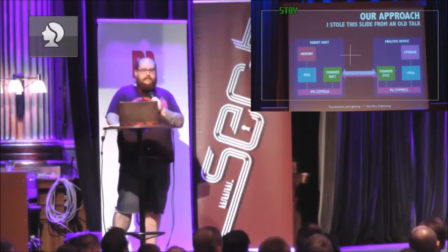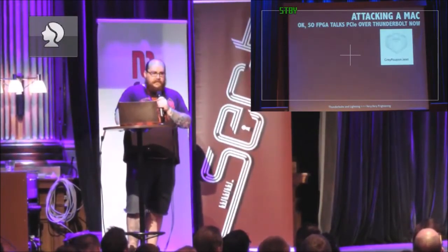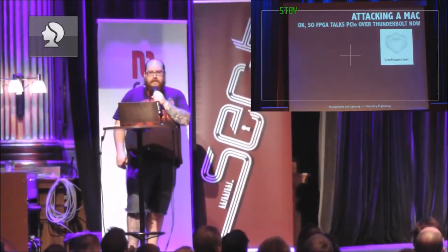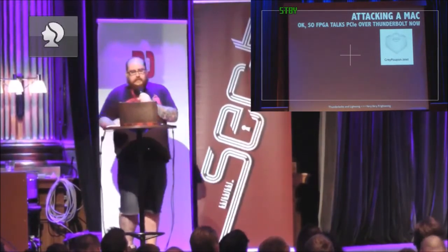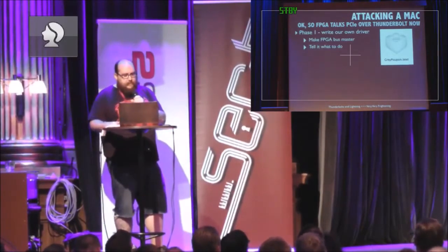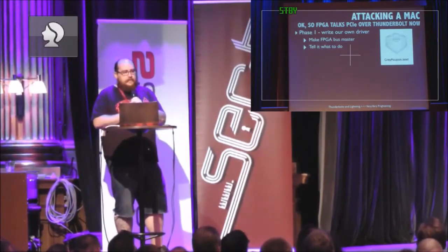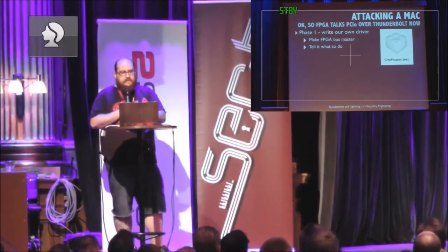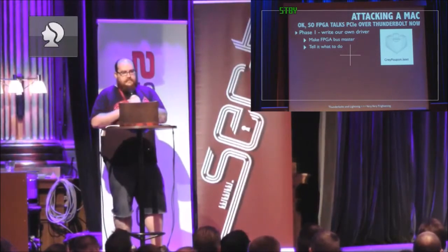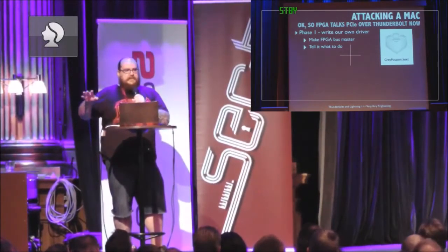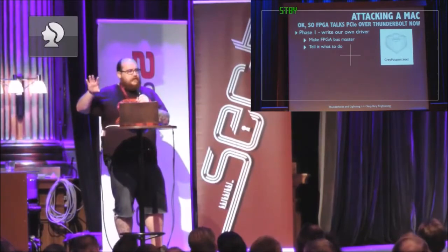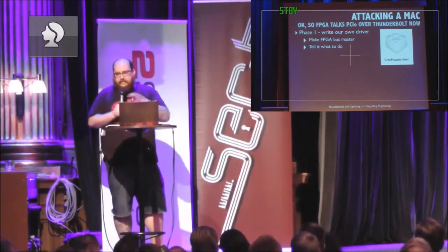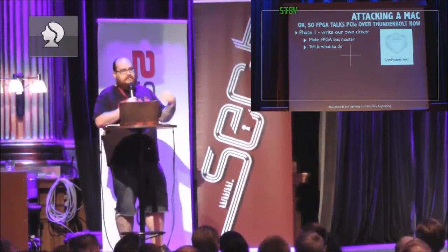Okay, so, actually attacking an operating system over PCI Express and over Thunderbolt. First of all we wrote our own driver. Just to get the development side of this done, we wrote our own driver that we load on our target machine to cheat and talk to the FPGA via PCI Express to configure it and tell it to do some stuff. This is before we had the MicroBlaze design done. We had just a state machine that told the PCI Express thing what to do.